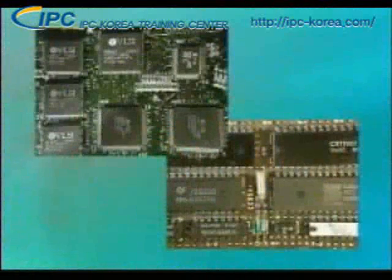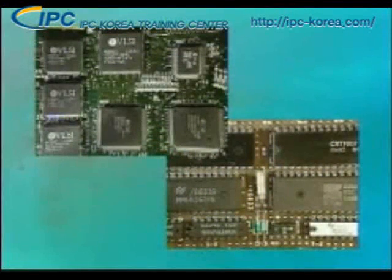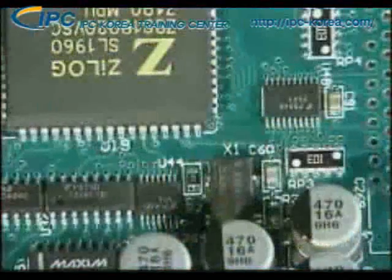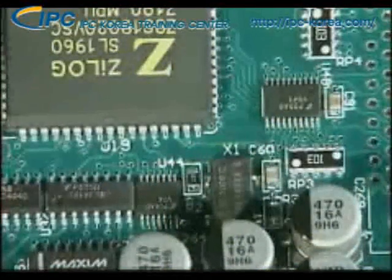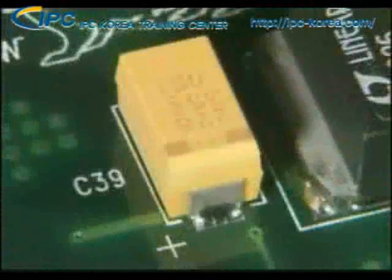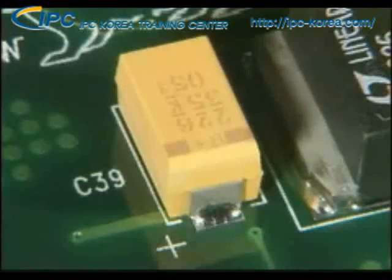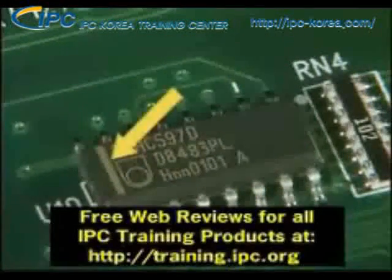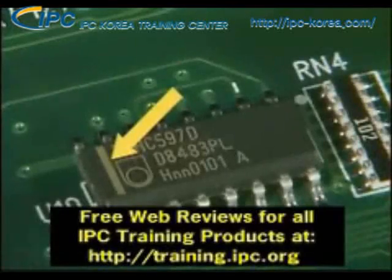What this means is that more electronic components and functions can be present on a small-sized circuit board when surface mount components are used than when through-hole components are used. Surface mount devices use the same system of part numbers, reference designators, and component values and tolerances as through-hole components. And the indicators for polarity and pin 1 orientation are also similar.